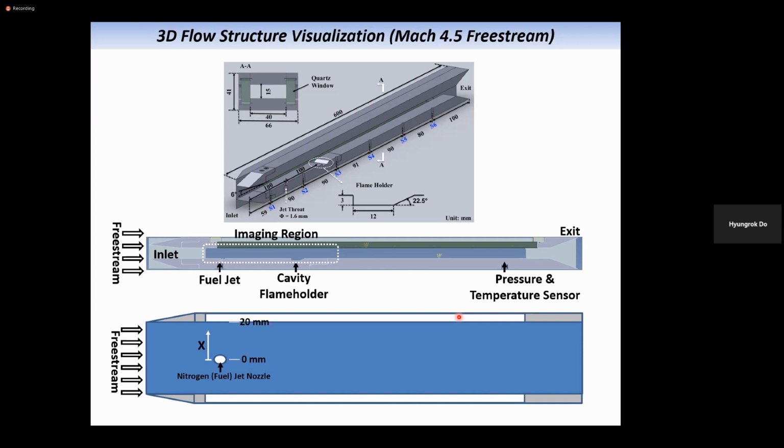For example, in engines, you want to measure something in the engine. So you should not put a diode laser into the engine. It should be outside. Your light source, like a diode laser or pump laser, should be protected from the high temperature, high pressure, or high speed gases. Okay? So that's why you need an optical access window. The optical access window is protecting your optical systems at first. So to protect your optical systems and detectors maybe, you will need to use an optical access window.